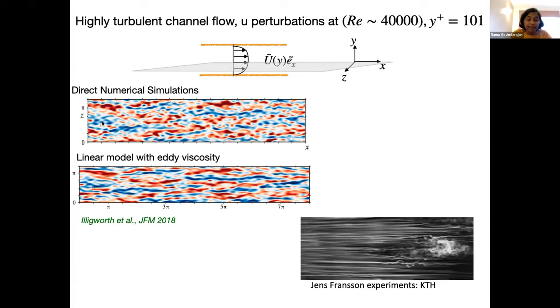And on that plane, you see the deviations of the u velocity, that means the streamwise velocity, from the mean in that plane. The mean is of course one number in that plane because y is fixed. You see positive and negative variations, and you see an overall streamwise alignment. It's not as random as you think. It's not like white noise. With white noise, you would see no structure whatsoever. There is streamwise alignment, and there is some characteristic spanwise spacing.